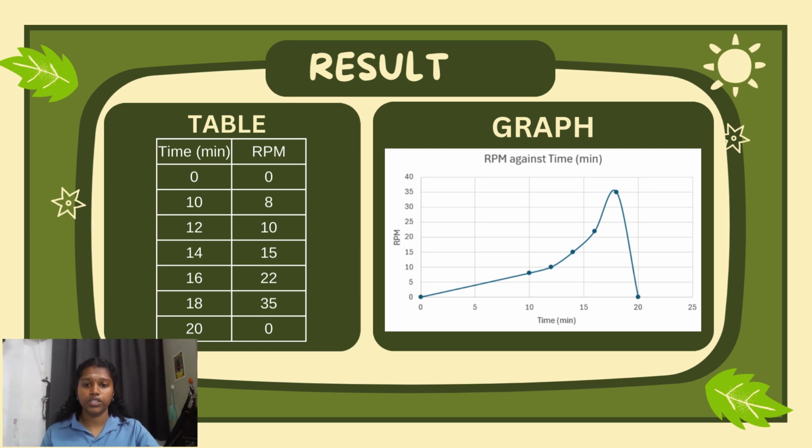Using a larger volume of water will increase thermal inertia and delay heating. The optimal water level balances heat absorption and vapor generation rates. By addressing this factor through improved design and installation, we could potentially reduce the initial delay before steam generation and rotation begins in the soda can model.